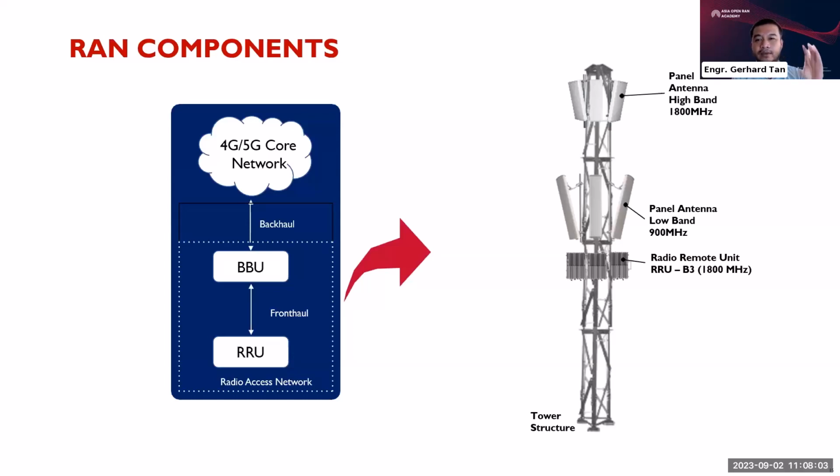That's why most operators now use the active antenna unit so that your RRU will be much nearer to the antenna, and of course, it uses fiber optic cable, so that your antenna will optimally deliver the power required to drive and propagate the signal a bit far, to cover more. Now, your BBU, on the other hand, is located in your telecom room. This is the one responsible for processing your signal before it transmits towards your backhaul or transmission media and then traverses towards your core network.